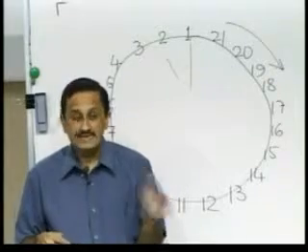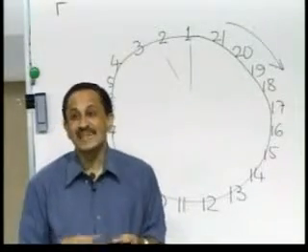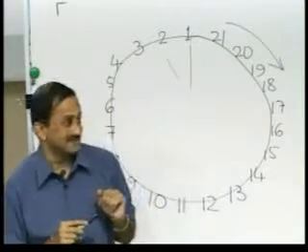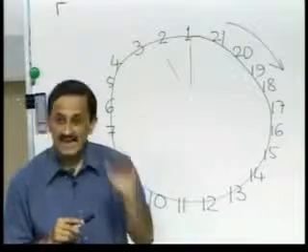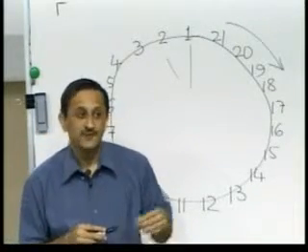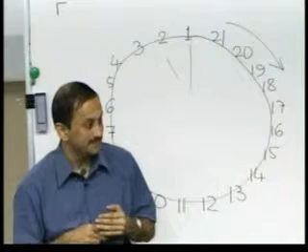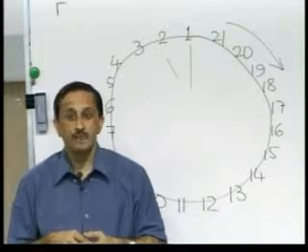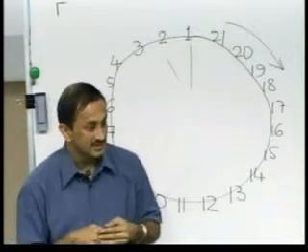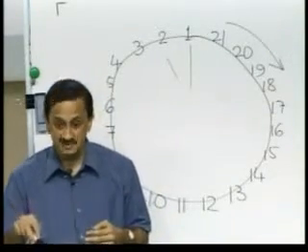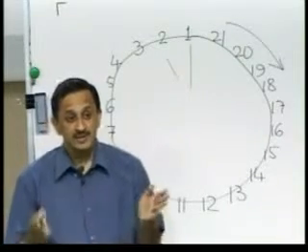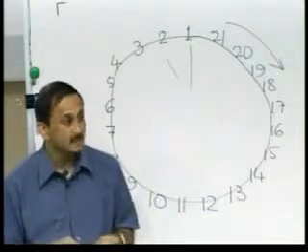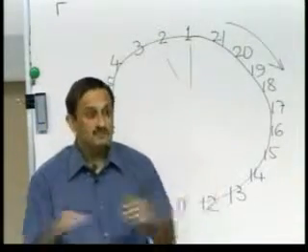Of course, it is not entirely the visual system, it is also the camera at times, and that sampling rate might fall short of what is recommended by the Nyquist principle, and therefore the wheel might appear to rotate in a direction opposite to its actual direction of rotation, and what is more, with a smaller speed. So there are two things that deceive: the speed and the direction, as we saw last time with the example of a sine wave when we looked in the spectral domain.